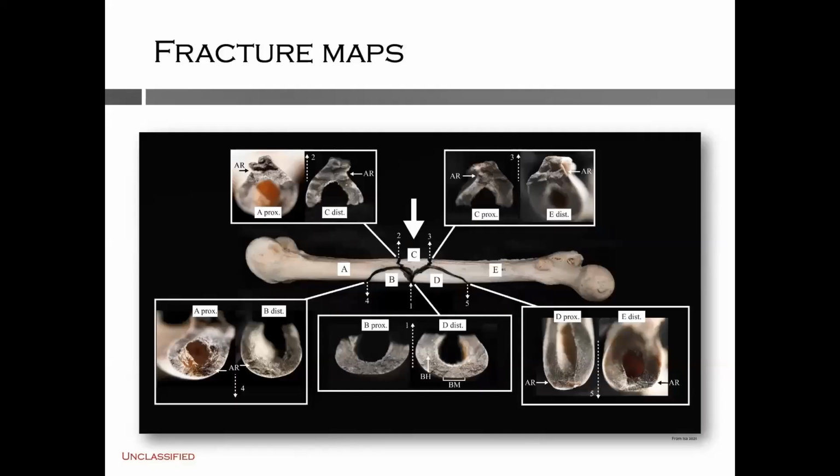A fracture map is a montage that's composed of local images that show smaller fracture details that are organized systematically around an overall image. Overall images are important for orienting viewers and showing larger patterns of fracture, but they're not able to communicate those smaller features effectively. So a fracture map is useful in that it helps connect this local information with a global interpretation.